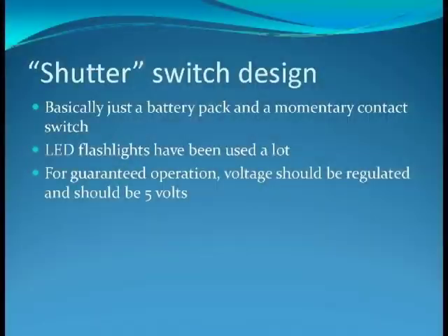Some of these cameras will work as low as 3 volts. The A570 has a buffer circuit built in it. If you plug a 9-volt battery into it, it'll probably take about 6 months before the camera stops working. It will stop working though. You don't want to over voltage these guys.